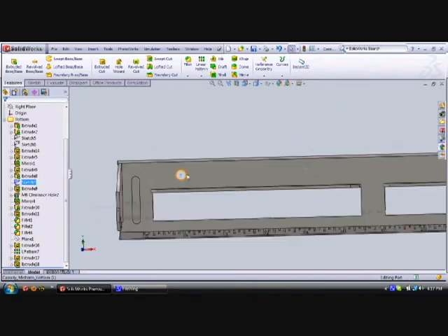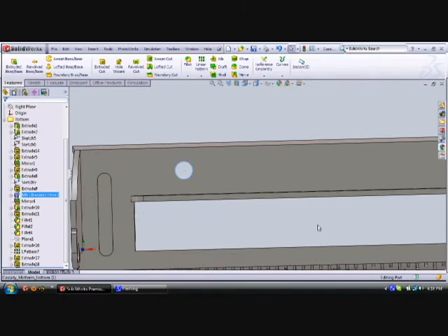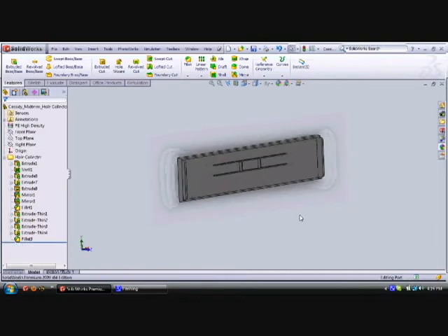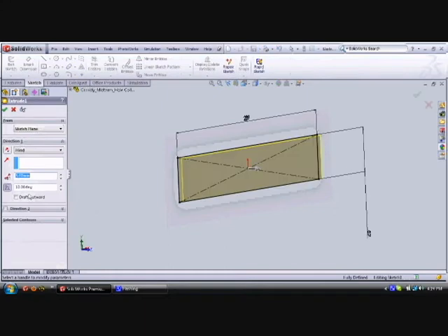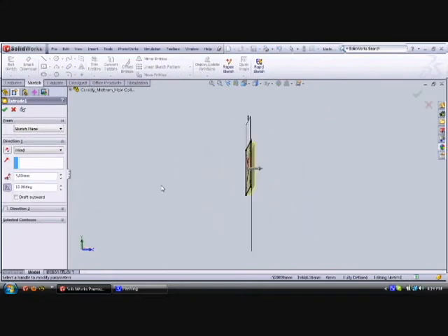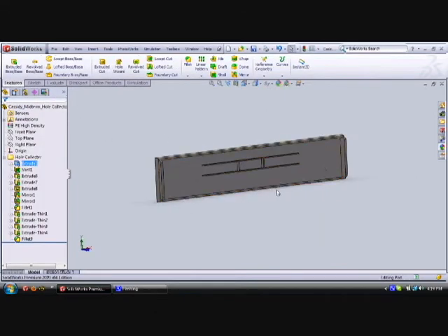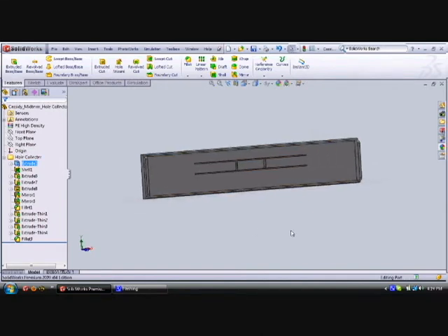I created a sketch to make sure that my geometry was correct and then made a hole that fit the geometry. Here we see the hole collector of the 3-hole punch. I used an extrude with the draft feature to get the draft that ultimately makes it connect to the bottom of the 3-hole punch. I then shelled it out to create a uniform thickness and used the extrude thin feature to create each of the lines on the inside of the hole collector.